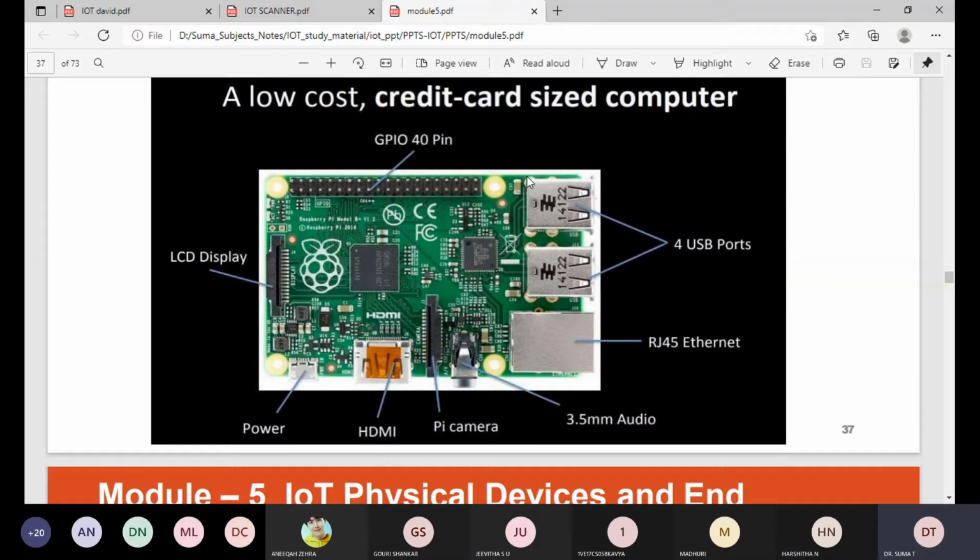The Ethernet port is controlled by the Microchip LAN9512 LAN controller chip. Then we come to the CSI connector. The Camera Serial Interface is a serial interface outlined by the Mobile Industry Processor Interface Organization for interfacing computerized cameras with a portable processor.